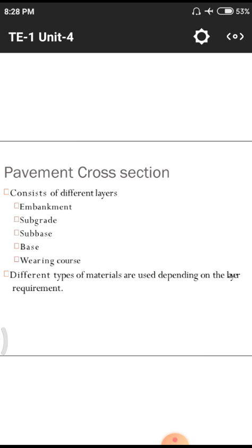Likewise, we have to use some plastic membranes, which have the capacity to prevent water from entering the road surfaces. In the surroundings of the roads we have to use these plastic covers in the base course of a road. That means after the top layer is over, in the embankments we have to use these plastic covers. On the top surface of the plastic cover we have to use some material for filling, so that it helps us control the entrainment of water into the substructures below the road.